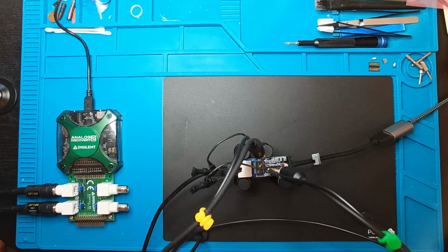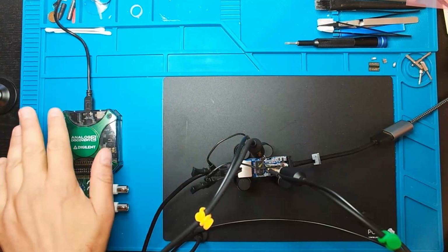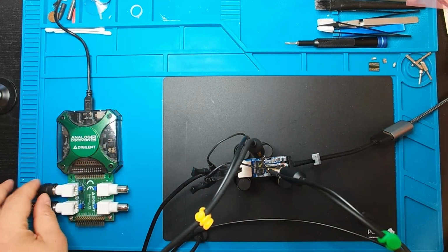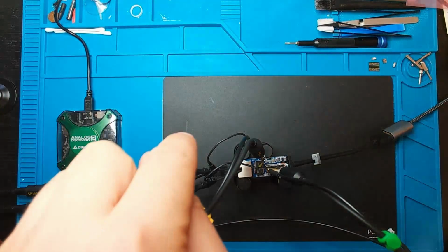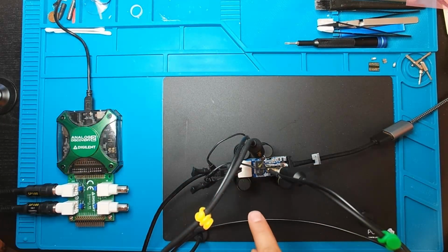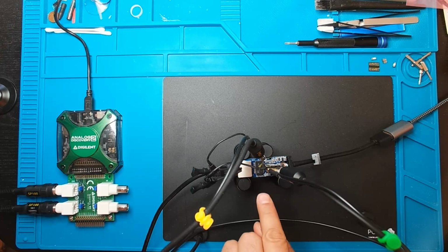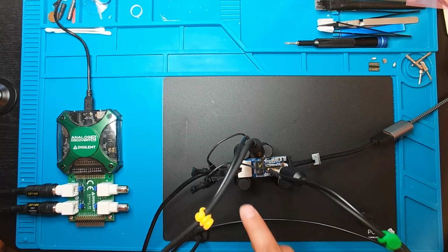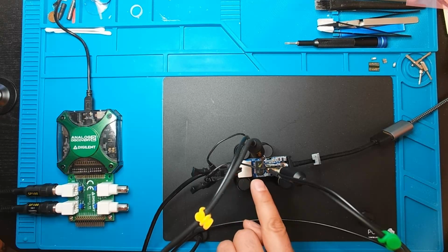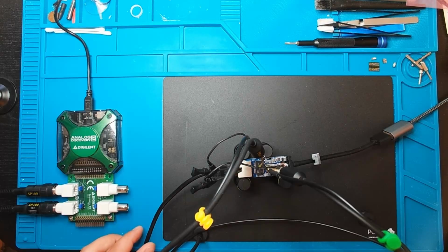Okay, here you can see once again the setup. We have the USB scope with the 2 channels connected to those 2 probes, which are connected to the TX pair directly here on the PCB board before the magnetics, but after the chipset. Here we have the ground connected of each probe, and we have an Ethernet cable which goes to the opponent PC.